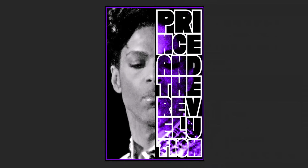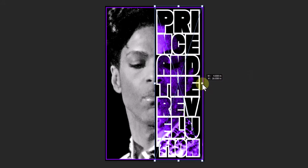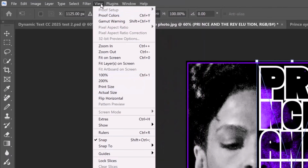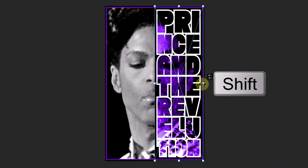In this case, I'd like to squeeze the text to the left a bit, so I'll press Ctrl or Command T to open the Transform tool. I'll place my cursor on the middle anchor point on the right side and press and hold the Shift key as I drag the text to the left. If the text is sticking a bit, go to View and click Snap to disable it. Now, when you drag it, it'll go where you want.